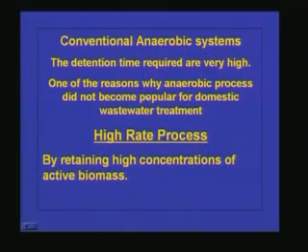So the anaerobic process has many advantages over the aerobic process, but the most important disadvantage is this one: it takes a large detention time to get high efficiency. So if we can overcome this, the anaerobic process will definitely become popular. So to avoid that, or to make the anaerobic process popular, people were working in this area for a long time, and they have come up with these high rate processes.